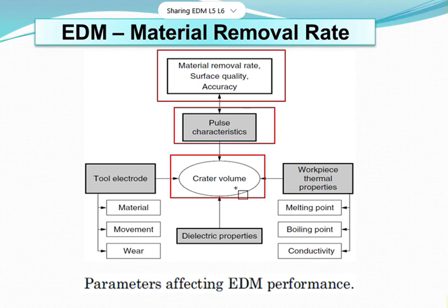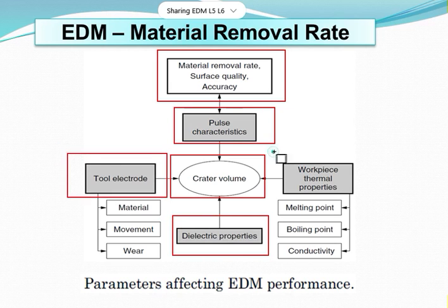While crater volume is also associated with the dielectric properties. This crater volume is created with the help of the tool electrode and the workpiece thermal property too. The tool electrode is associated with material, movement and wear, and the workpiece thermal properties include melting point, boiling point and conductivity.